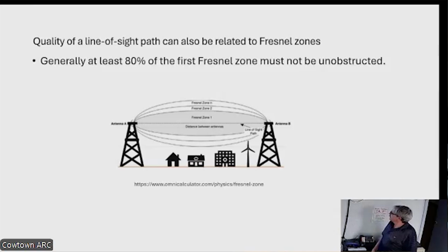If you double the frequency, the zone should get shorter, because your wavelengths are getting shorter. This is important in these systems because of weather-dependent ray refraction that occurs in the troposphere. The waves aren't necessarily propagating in straight lines; they're bent by the atmosphere, the troposphere in particular, because the refractive index is changing.